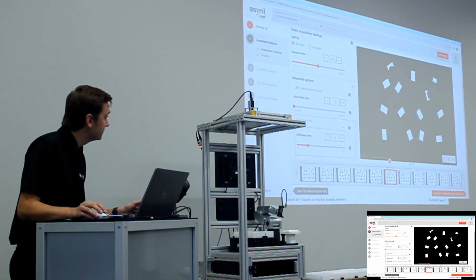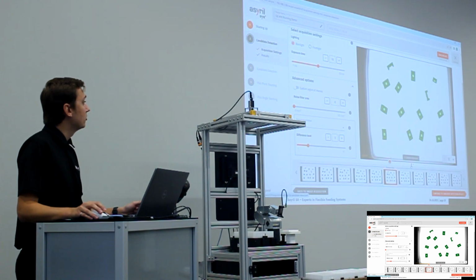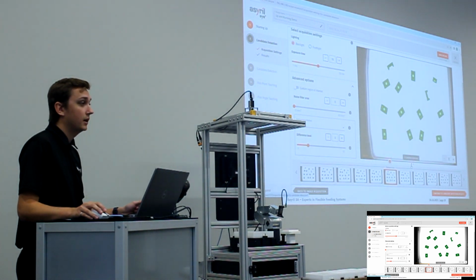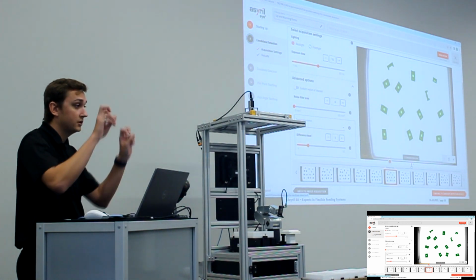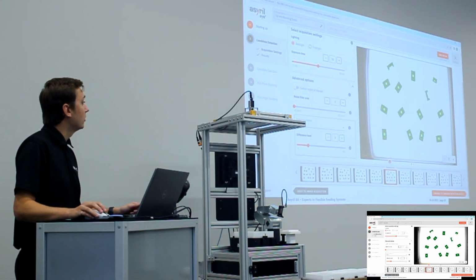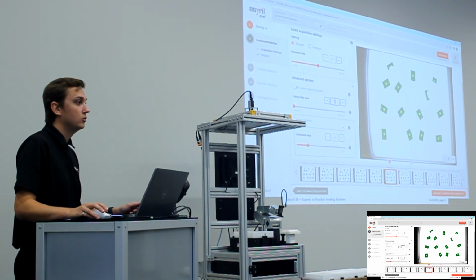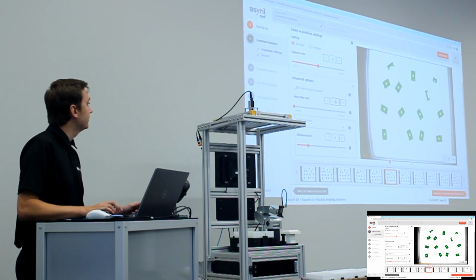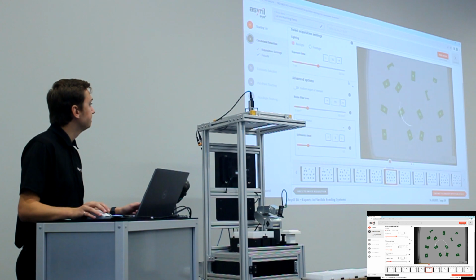and get rid of some of that noise here. And so sometimes if you've got a slotted platform or too high of an exposure level, you'll pick up some of the platform edges as a part. It'll define it as a green zone. And so we want to just make sure that we only have the parts on the platform. And we can create a noise filter here to remove any particles on the platform. We'll just go like 15 square millimeters here.